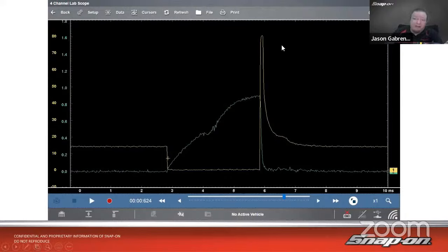If I don't get a peak at all, that indicates it really didn't open because my coil didn't hold that energy. It works on the same principle as an ignition coil. Then it comes down, and then we have this other little pintle bump right here. Now, this is going to be the actual point where the pintle closes, snaps shut, and stops spraying fuel. When it does that, that little mechanical stop jolts a little extra juice back out of the coil, so we get that little thing they also call coil oscillation, and then it flattens out.